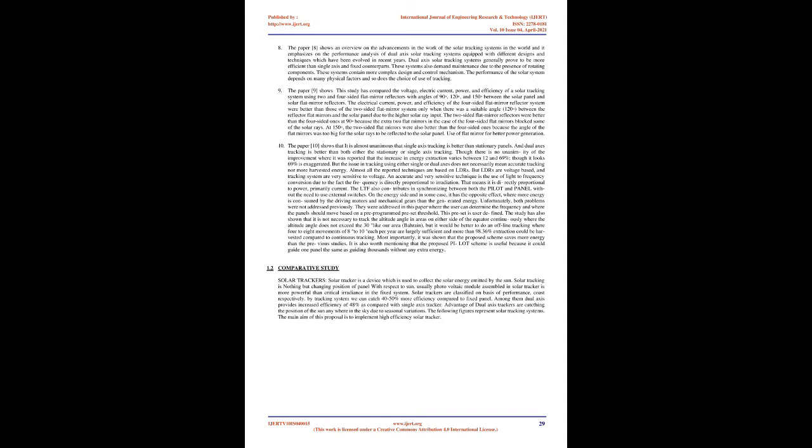Furthermore, the tracking panel reduces the losses caused by the curved trajectory of the sun, which starts and ends at the back of the fixed panel. This type of loss in the fixed panel can be observed in the months of October and November, when the average daily irradiations are lower than those in the previous months. Considering the period from June to November, the irradiation data were collected on a panel mounted on a fixed structure and another one equipped with a tracker mechanism.